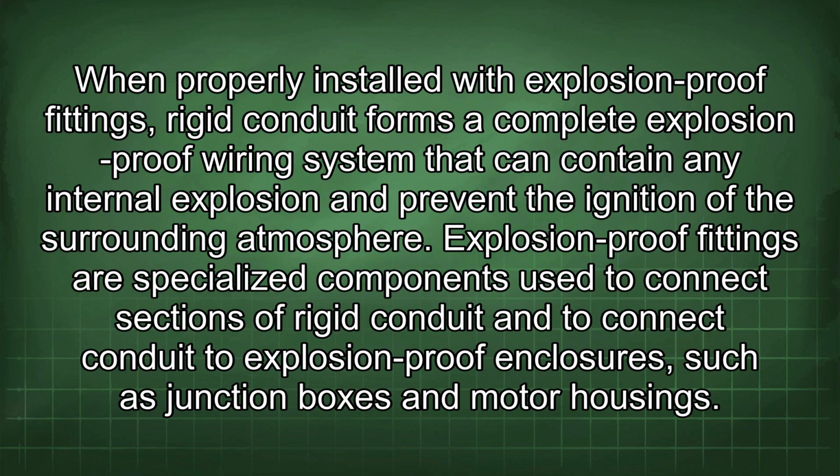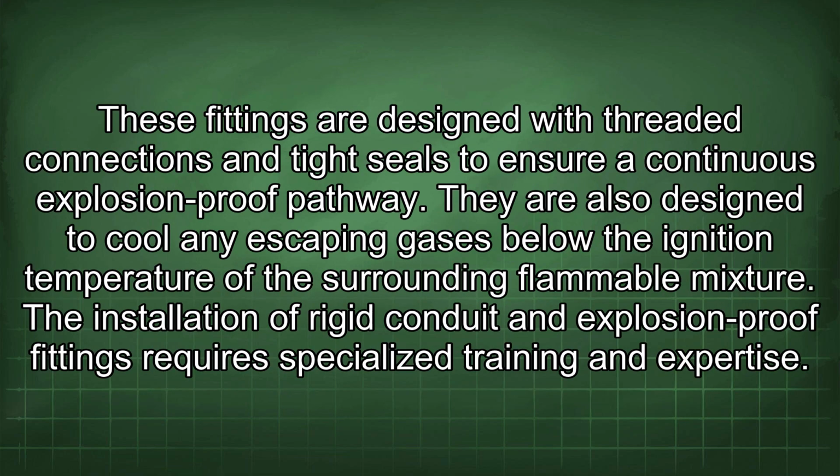Explosion-proof fittings are specialized components used to connect sections of rigid conduit and to connect conduit to explosion-proof enclosures such as junction boxes and motor housings. These fittings are designed with threaded connections and tight seals to ensure a continuous explosion-proof pathway. They are also designed to cool any escaping gases below the ignition temperature of the surrounding flammable mixture.